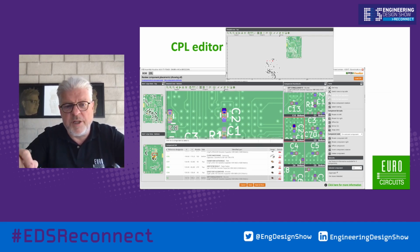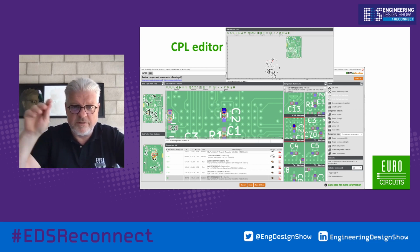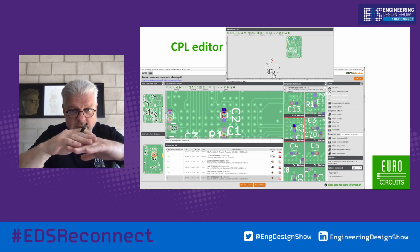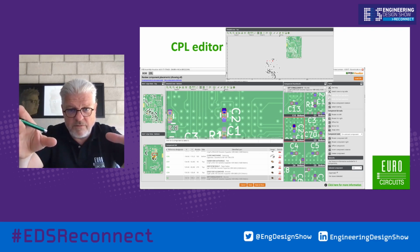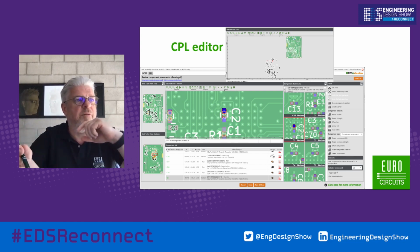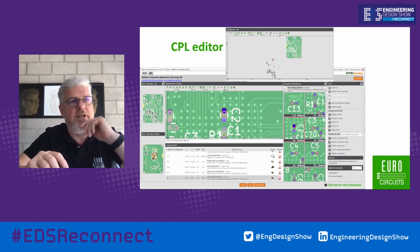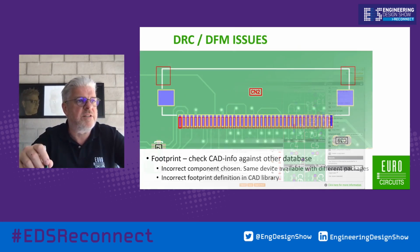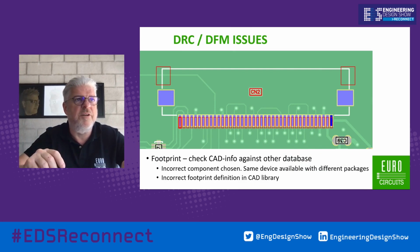The CPL editor. In the CPL editor, we read in the placement data, and CPL stands for component placement list. We place the components that we found in your BOM list on the set of Gerber data. We are not yet in the stage of the order. We are still in the stage of dealing with your data in the communication before we make something for you. And this is interesting because here we can, of course, check if everything fits together and if the footprint of the component also aligns with the Gerber data underneath, which in many cases it doesn't, like in this case.